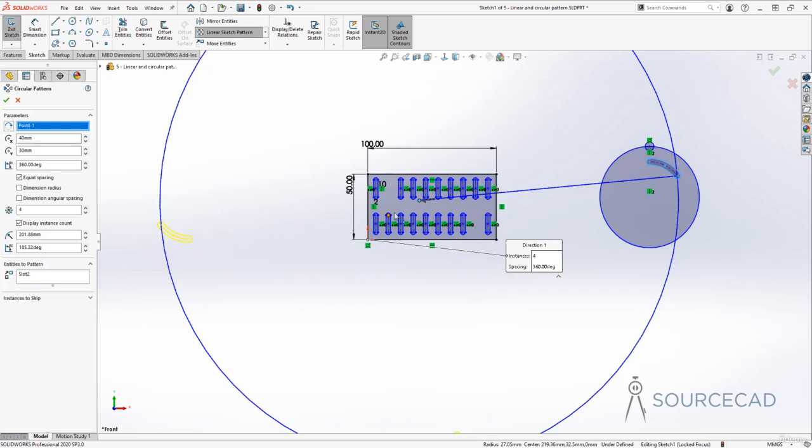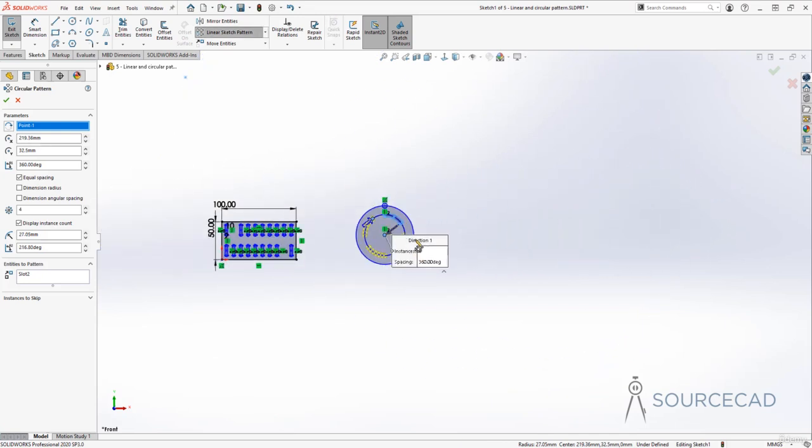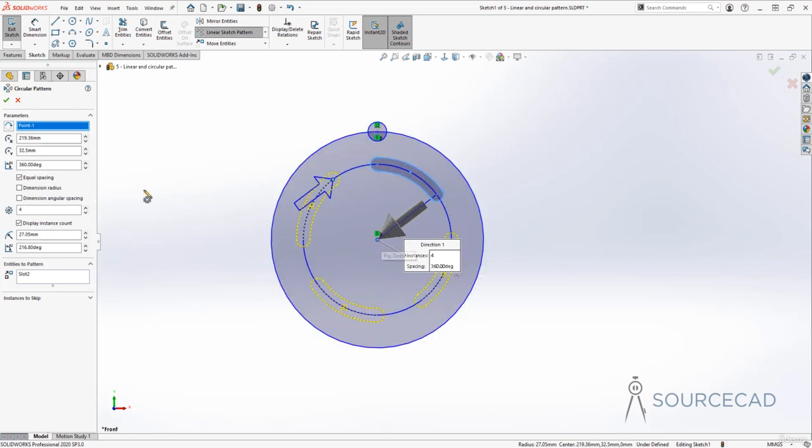The first one is this center point. I want to move it exactly here. In order to do that, you can just grab this point, and if this point is at origin, you can just change its coordinate values ever so slightly, and when it's off, just grab this and move it here. All right. Now our point 1 is exactly where it should be, and the coordinates of that point will be filled automatically.